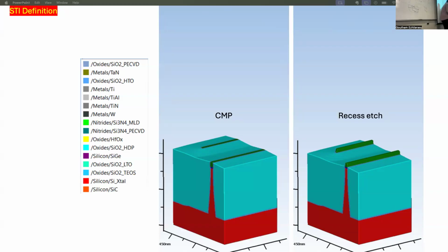Yeah, it's just process. So usually, when you etch something, imagine you had something like this. That's how deglazing works. If you have some feature like this, say this is oxide, then when you do a blanket etch, the things that are sharper tend to etch slightly faster than the things that are flat. So this roughness had some amplitude, and when you do this kind of dry etch down, this amplitude reduces, because the sharper places tend to etch slightly faster. That's why, when you do this deglazing step, here the slope was higher, but here it's not as high.